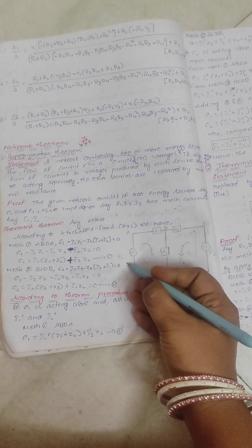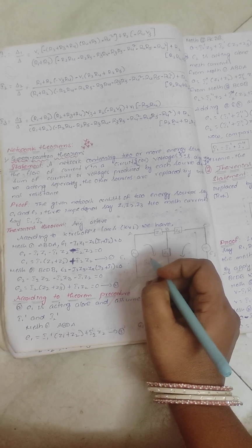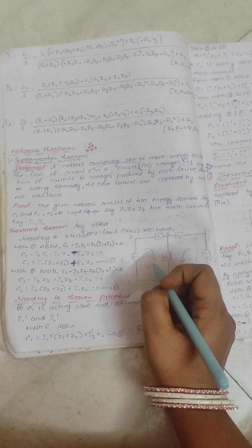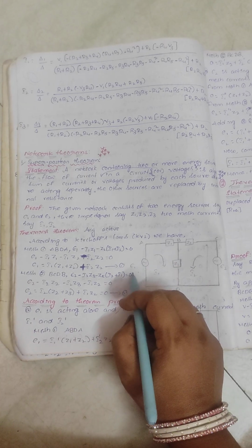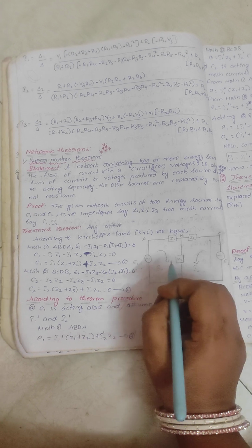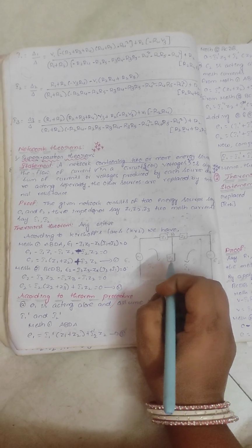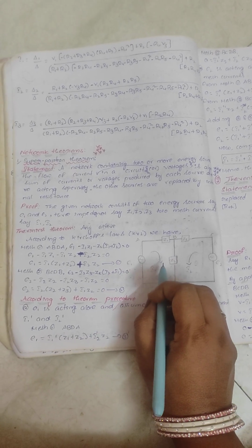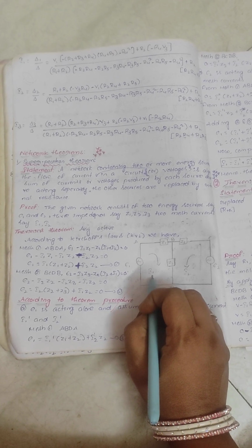E1, in which direction is it? It is in clockwise direction. If it is in clockwise direction, we have to take it as negative. If it is in anti-clockwise direction, we have to take it as positive. Next, E1 minus I1 Z1, minus Z2. Z2 is related to this mesh and also this mesh. That's why we have taken both the currents: minus Z2 because it is the clockwise direction, minus Z2 into I1